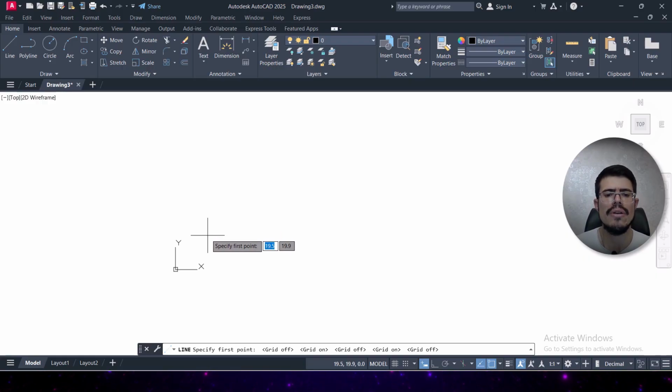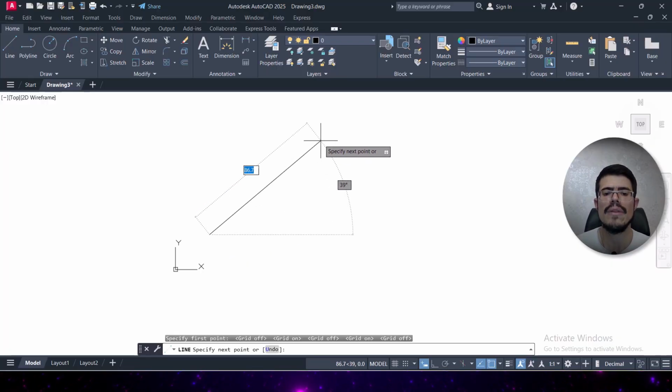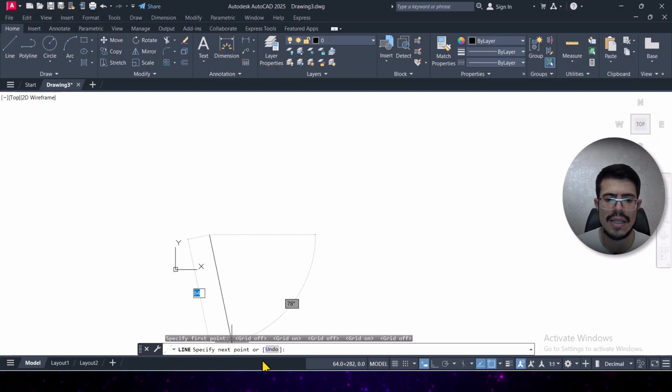Now I choose manual points, not exact ones, from here. I choose the first one. Be careful when selecting or activating the command: I told you we work with left click. Now I press it. It's the start point. For making a line, we need 2 points, so we need 2 coordinates. We set the start point. Now we have the next point. If we want to make just one line, we can call it the end point. Now it says "Specify next point," as you see here.